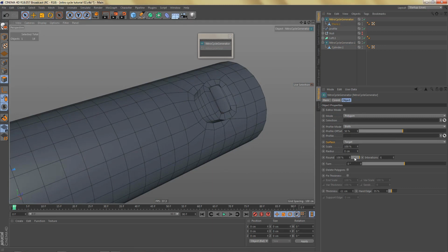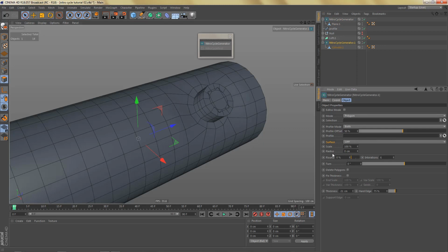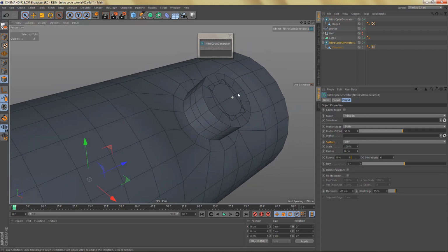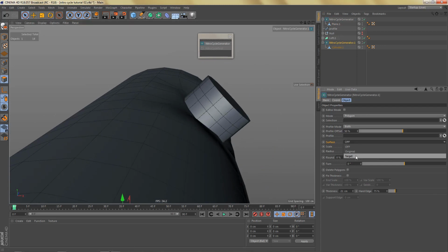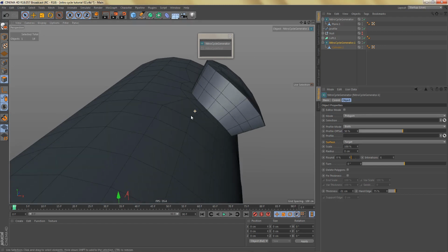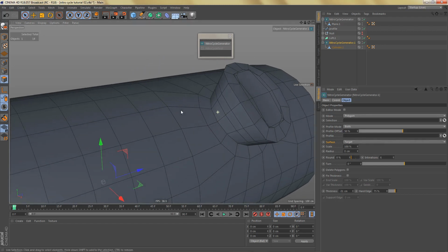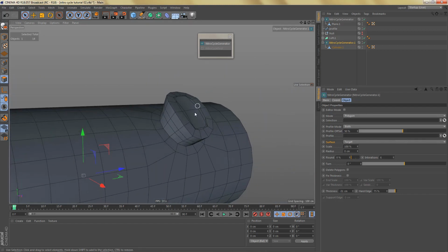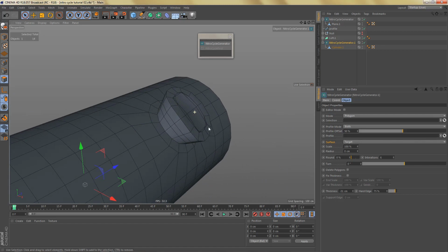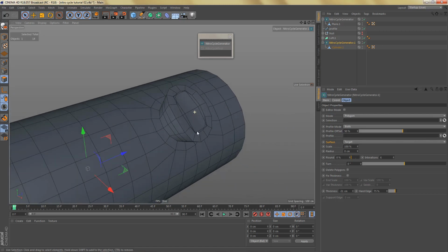And hopefully I can show you the fix thickness option here. So let's see if we can make this a little rounder. I also want to switch the surface to target, so you can see the shape gets adjusted to the curvature here. And you can also see that our extrusion changes, and it's not really circular anymore.